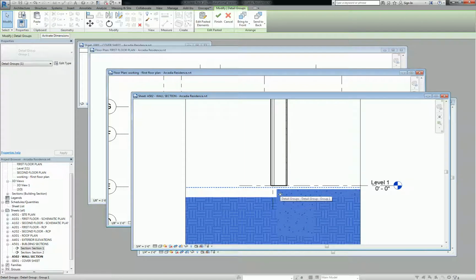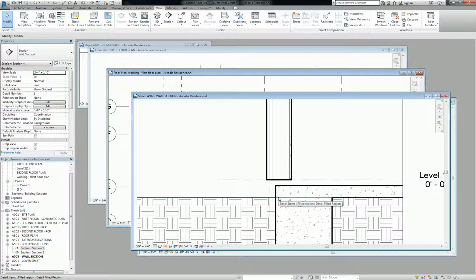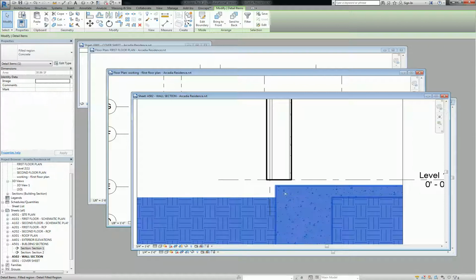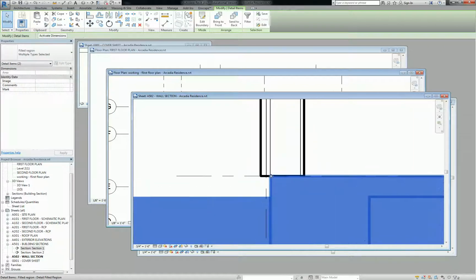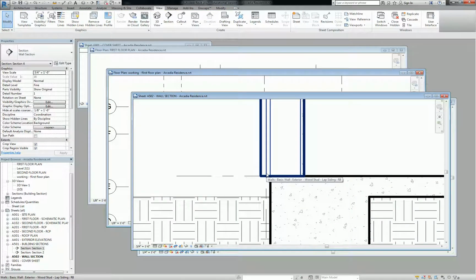Now, at this stage, you do need to be careful about some level of detail because I have a slab and I have grade, and I need to know where the slab goes relative to my wall. So a lot of exterior assemblies will actually have the slab go up to the edge of the stud, and then that exterior wall layer will extend down and kind of cover things. And usually you need to have 8 inches between the two, but we're not getting down into that level of detail right now. Okay, I just want you to get close to something that's accurate.